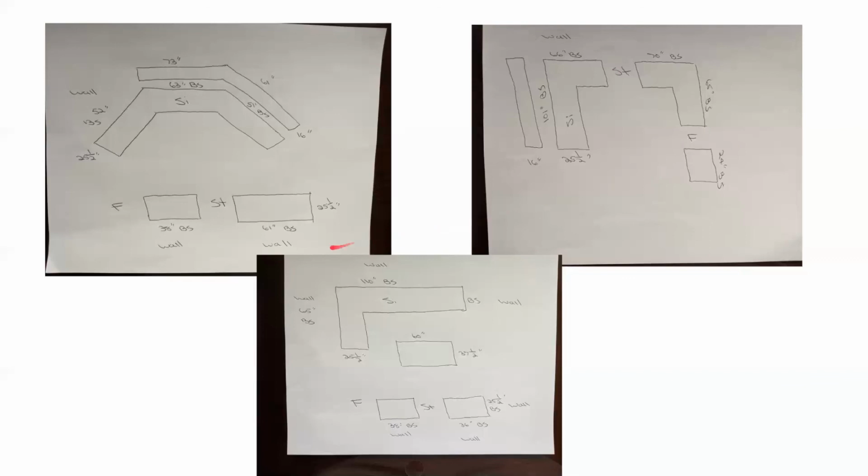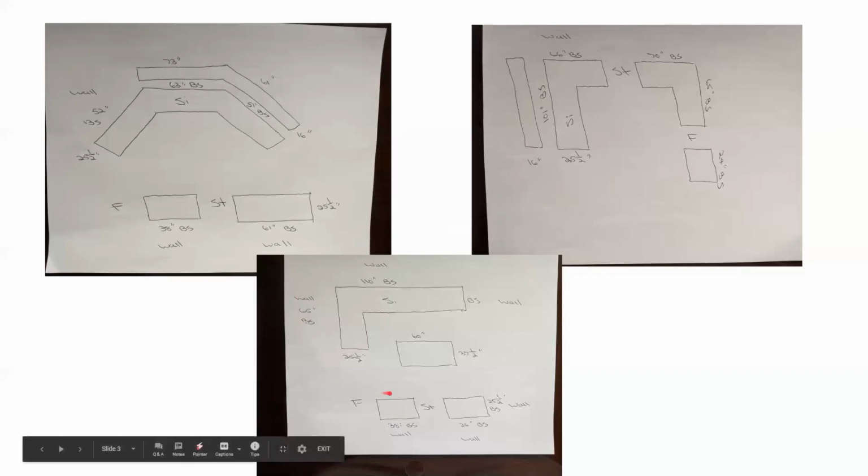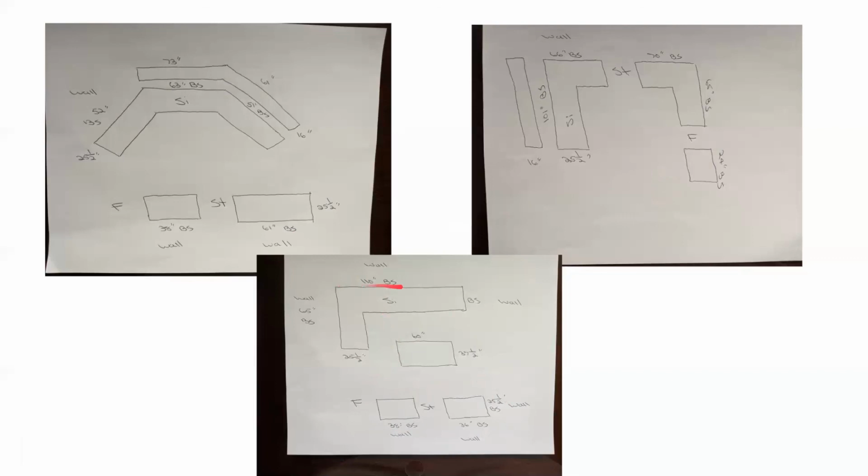And then the final one here is an L-shaped kitchen that includes, I should say, an island and also two sections on either side of a stove. And so same exercise, back wall dimension here. There is a wall, 110-inch length with a backsplash. There's a wall on this side here as well, and we'll include a backsplash. And then we also have a wall on this side, the 65-inch length with a backsplash, all 25.5 inches wide.